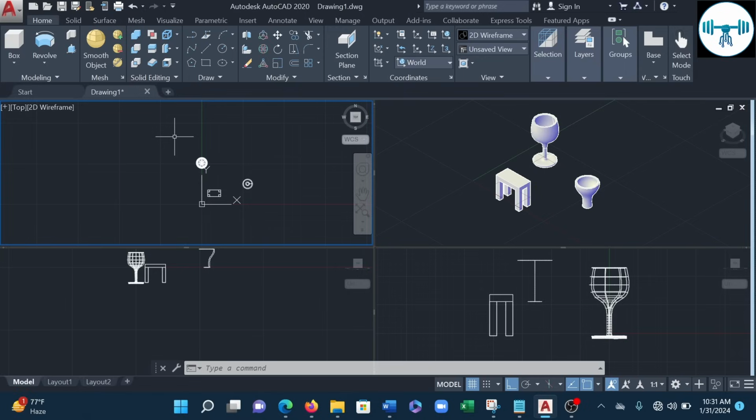Or we could just use a straight pipe. Let's use a straight pipe for this particular lesson. Subsequently we can design more complex pipes. Now for our sweep, remember we said that two things are very important in sweep, and those two things are your profile and your path.